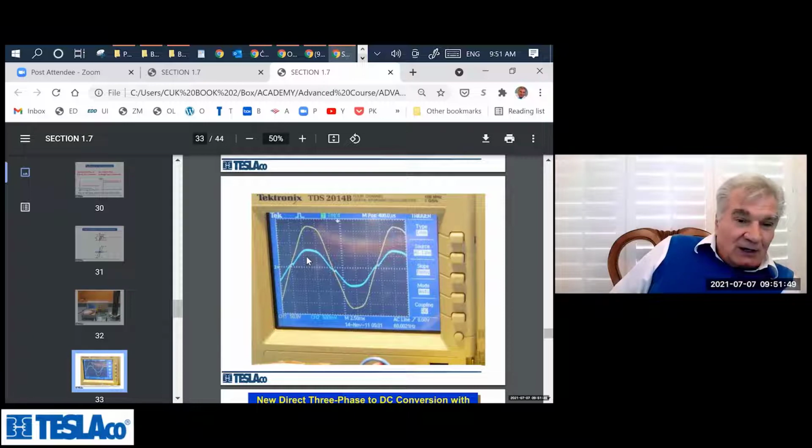If you don't, the utility should actually be motivated to install this in all new homes because they would be saving money. For a big industrial outfit, they measure the power factor and say, oh, you have a bad power factor of 0.7, you pay 50% more for every kilowatt. But they don't do it for residential. So that's another thing where there's a lot of waste.